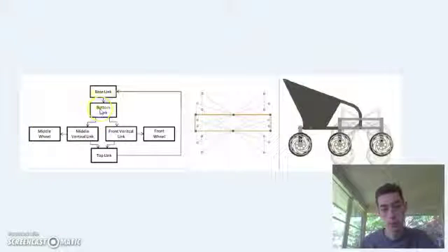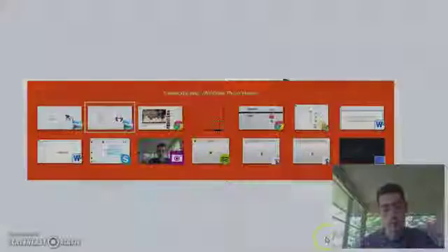So for our export process, we're going to try to make this closed kinematic loop an open kinematic loop, and then add the joints later. We can either do this by going from the bottom link to the wheels, or from the top link down to the wheels. It doesn't really matter in this case.